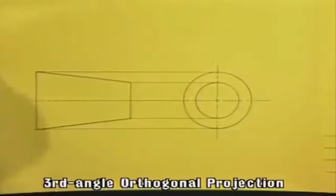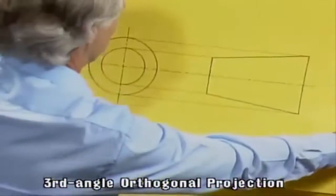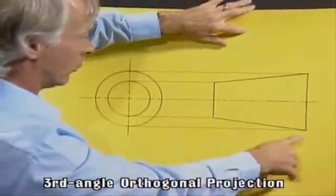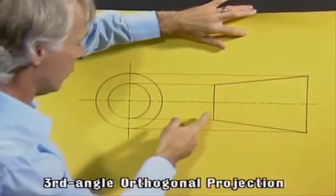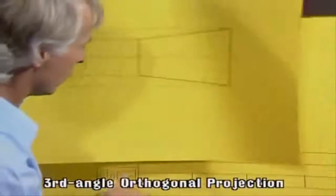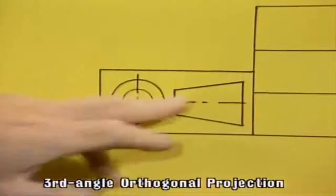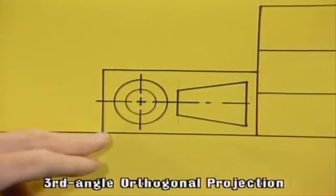The same symbol could be shown the other way up. So the truncated cone could be shown with the narrow end to the left, in which case we've got the 2 concentric circles shown on the left-hand side. It's shown in the title block in that position. That depicts that we've got a third angle projection drawing.